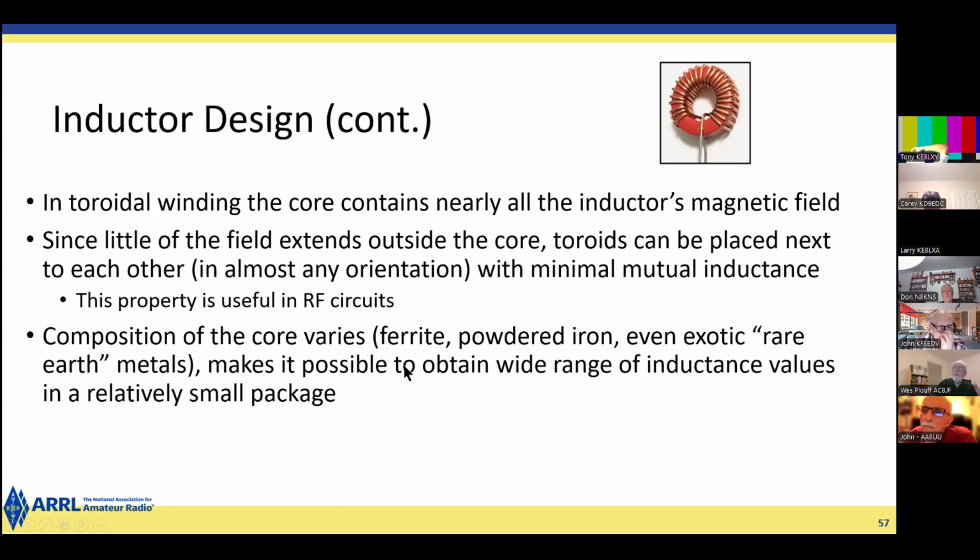Also, for what it's worth, ferrite compounds are more effective at certain ranges of frequencies. So you'll see people talk about the mix of the core, the ferrite mix of the core. And some of them are better suited for the lower ham bands, some of them for the upper HF bands. Some of them are better suited for a relatively narrow range of frequencies, and some for broader ranges. And that's a bit of a black art. But you'll see people choose different kinds of cores depending on the frequency and the application.